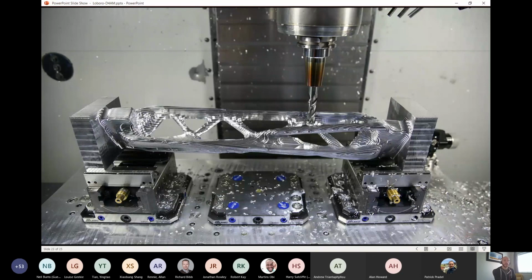If we look at machining this part, we're actually fortunate because we have these very easy blocks on the end that make work holding quite simplistic. But at some point, we're going to need to machine these blocks off the end and then machine where that material was. So you have this very complex organic shape. How do you hold that part? When it comes to subtractive manufacture, that's a great example of an area where fixturing often makes up a significant cost of any project. So both designing and manufacturing fixturing to hold these parts whilst you machine them has some very serious implications to both time and cost of the project as a whole.